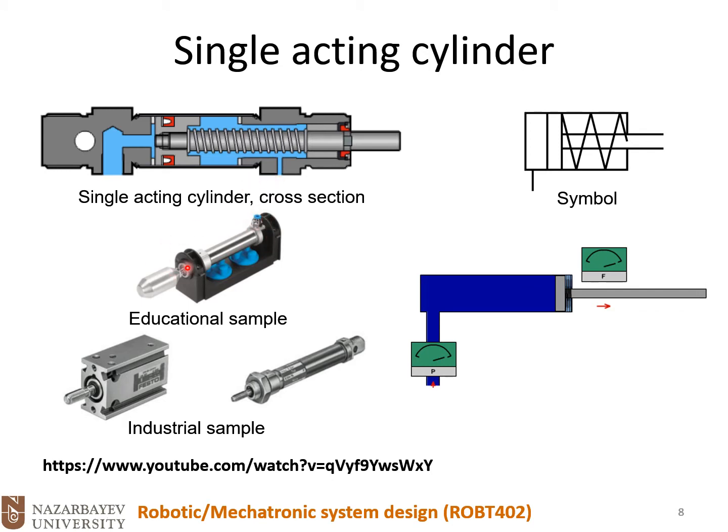Okay, so here you can see one educational sample of these single acting cylinders, and you see the main port here. By looking at the cylinders, the way to identify between single acting and double acting cylinders is finding the number of main ports. On this one we have one main port, and we could attach the pipe to this port. So this is a single acting cylinder.